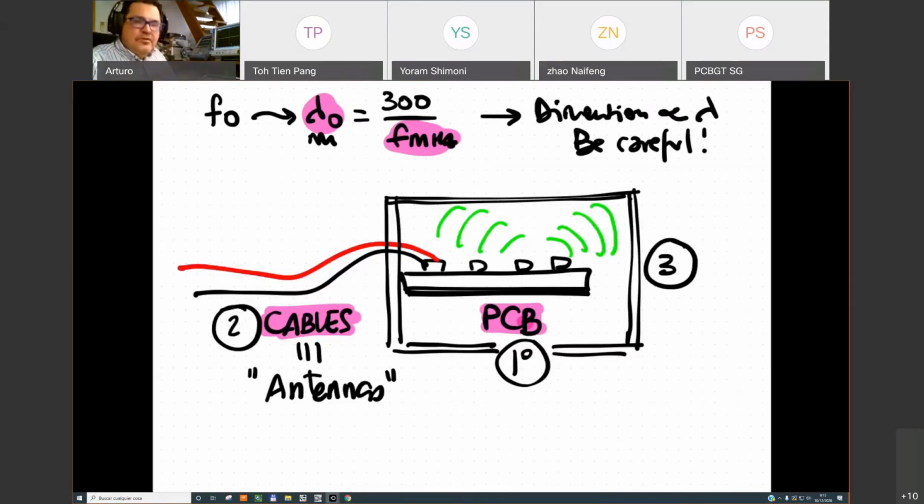But if you are not in this low frequency magnetic field situation, any kind of material is able to solve problems. So where is typically the problem with shielding? The problem with shielding is in this area, where and how you go in and out of your system with cables. Are you introducing some kind of filters in these cables?